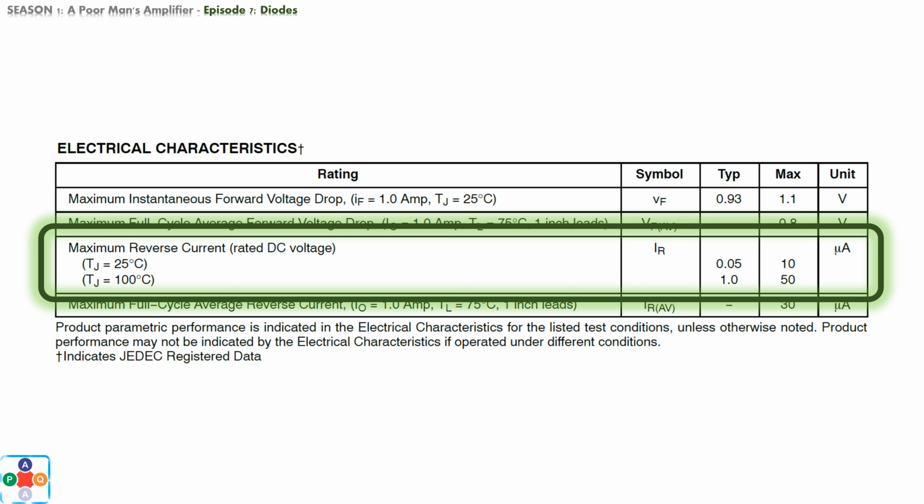If by mistake we install the diode the other way around, so that the polarization of the diode does not match the polarization of the battery, one would expect that there will be no current flowing through the circuit. This would be the case if the diode were what is called an ideal diode. Since there are no ideal electrical components, and in our case there is no ideal diode, if we install the diode incorrectly in the circuit and power the circuit on, there will be some small amount of current flowing through the circuit, nevertheless.